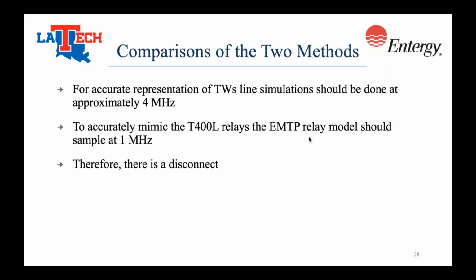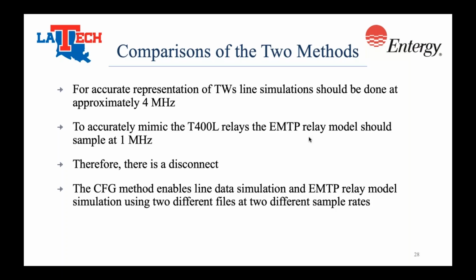This causes a disconnect because there are now 2 separate EMTP files required. If users plan to use only one sample rate, the ScopeView method is the most straightforward way to generate the Comtrade files. But if downsampling is required, the Comtrade files should be generated with the beta add-on blocks.